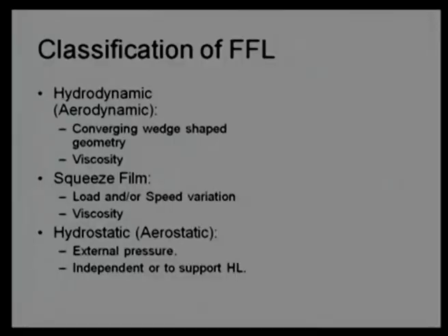First category says the hydrodynamic lubrication. In bracket it says the aerodynamic lubrication. The concepts remain same, only the governing lubrication media change. In hydrodynamic lubrication, it will be the liquid which will be used as a lubricant, while in aerodynamic it will be the gas. That is why to differentiate presence of liquid or gas, we say hydrodynamic or aerodynamic.